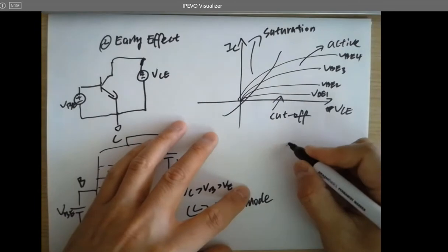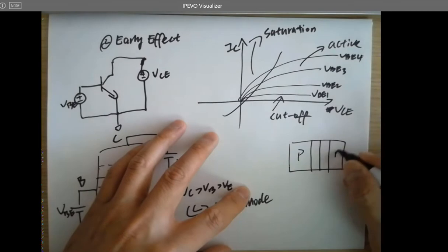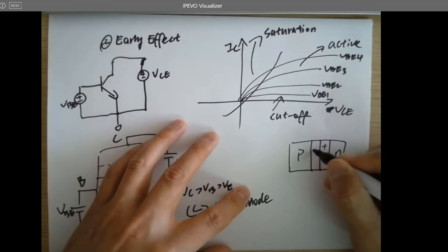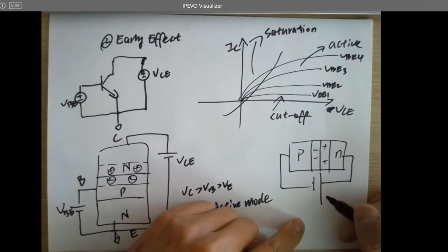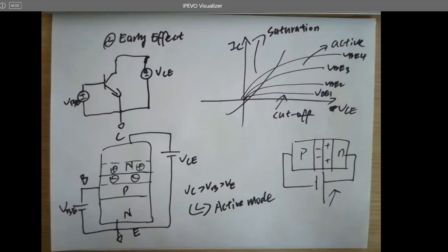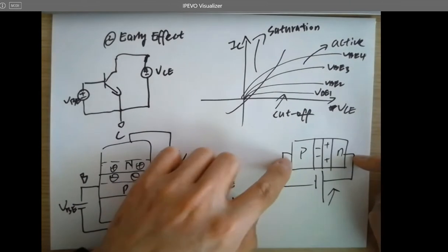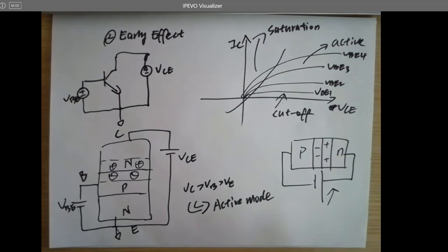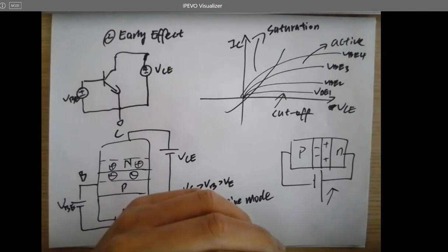Remember, we have done this in the diode. We have discussed this. So if we reverse bias it and increase the voltage, is this getting wider or narrower? Getting wider. Why? How can you remember that? How can you understand this intuitively? If you forward bias it, it's going to be conductive. Why? Because it's getting thinner and thinner, so the electrons can be swept through the depletion region, and so it can make the diode conductive. That's how that works, right?